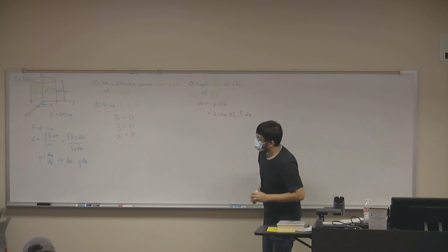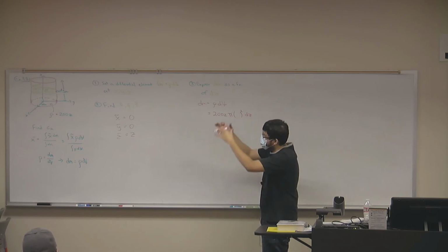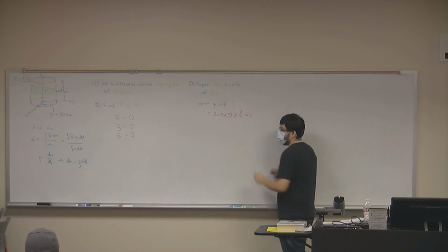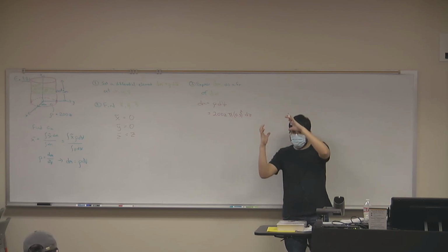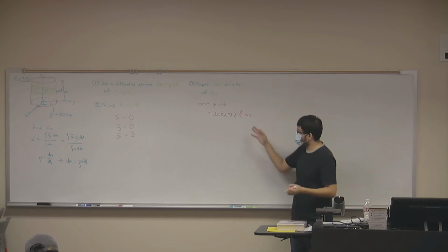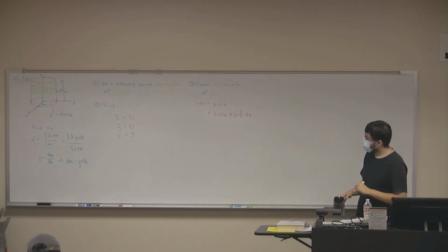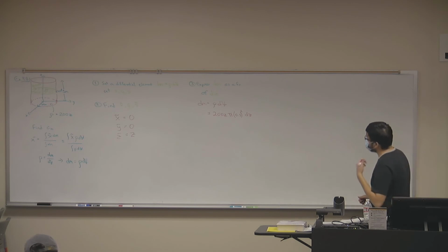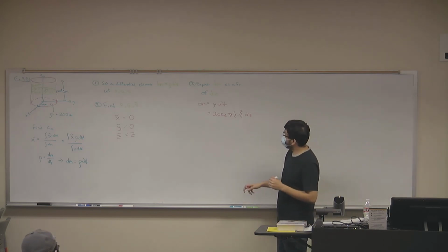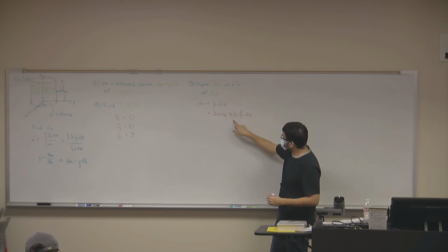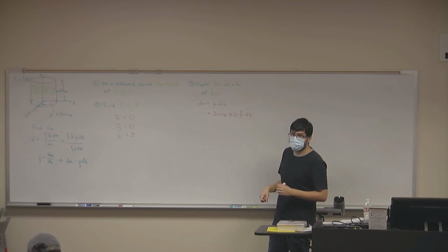And what's the radius of that plate? Regardless of where I place my plate, what's the radius going to be? 0.5, always, right? That doesn't change. In the previous problem, our radius changed, right? So we had to express our radius as some variable, I think y. But here, our radius is always going to be 0.5. So I always include it as 0.5. So I express my differential mass as a function of z, right? dm equals rho dv, rho equals 200z, dv equals pi 0.5 squared dz.